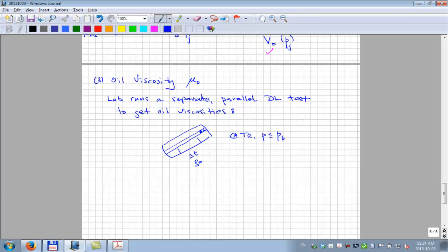Basically, you need to know the oil density, and together these give you the oil viscosity, typically within somewhere between 5 and 15%. That's about the best you can do. It's called a rolling ball viscometer. Okay, it's just a big steel thing that's got a hole in it. You fill a cylinder in it, and it's got oil in there and a ball, and the ball rolls down.